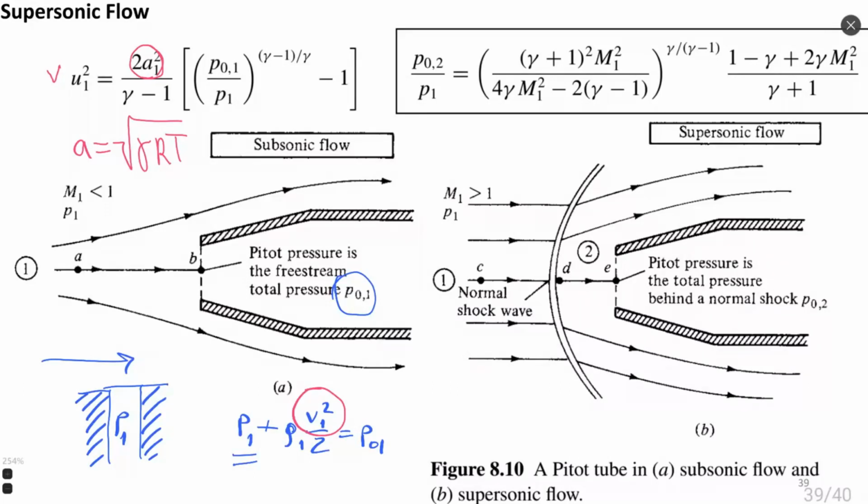In some cases, we do not need the temperature sensor if we know the altitude of flight and our system knows standard atmosphere tables, which have a relation between altitude and temperature, pressure, and density. It can take this data directly from the board computer and calculate speed of sound automatically without measuring onboard temperature, because if you're flying in different conditions, it can be a problem to measure temperature.